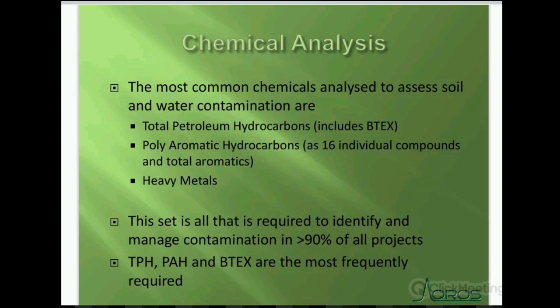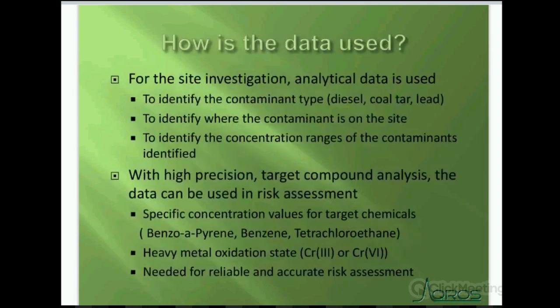Okay, that little set there is all that's required to identify and manage contamination about 90% of all your projects, and it's the TPH, PAH, and BTEX which are the most frequently required, followed by heavy metals.